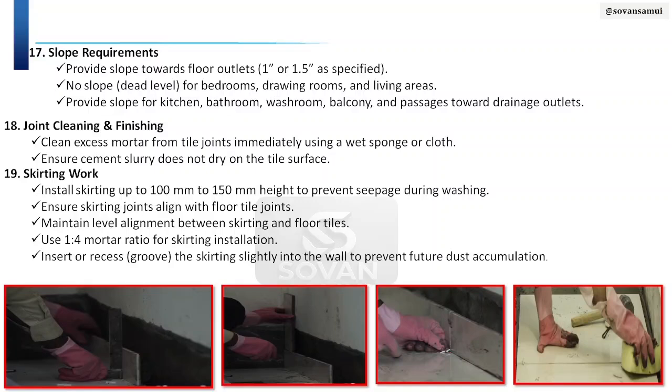Okay. Next point is joint cleaning and finishing. During tile laying or installation, the excess mortar should be taken out from the joint. That's why immediate cleaning is required, and if it dries, then those areas cannot be cleaned properly. That's why an immediate wash is required.